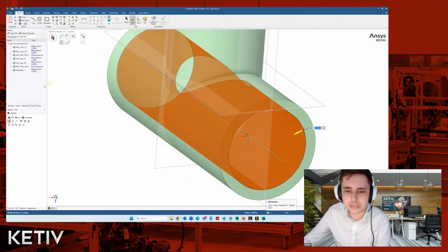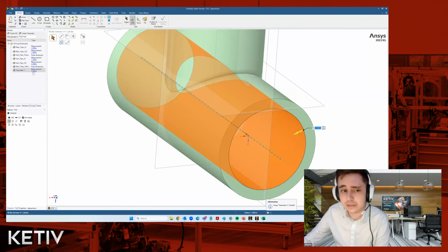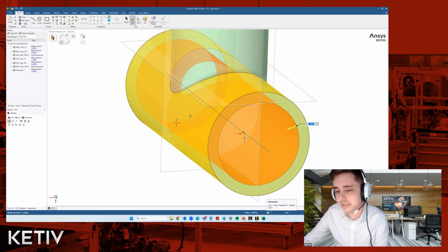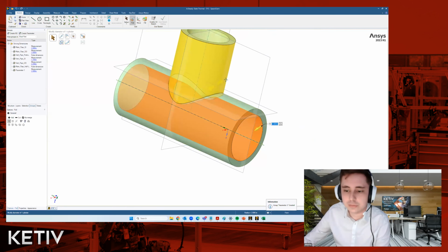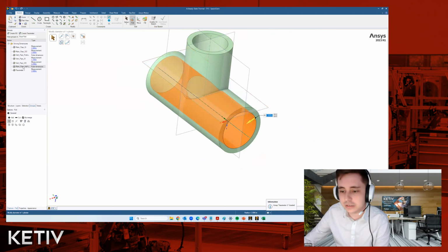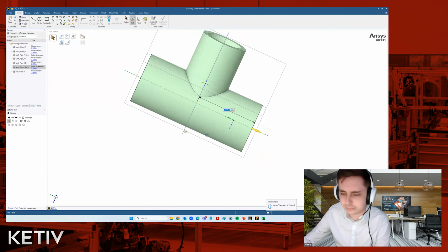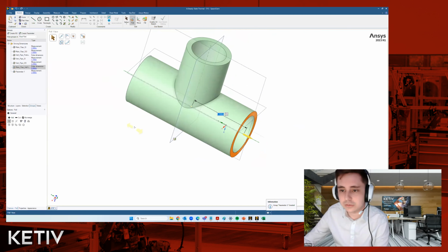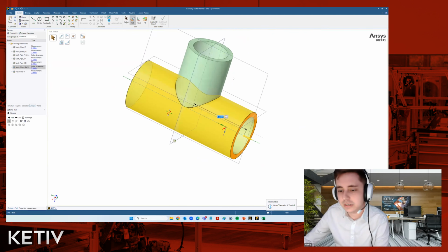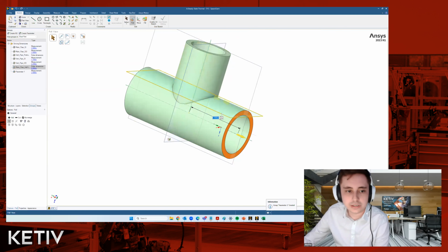So that's how you add any kind of parameter that you like. And of course, it can be much more complex than that. For instance, we have this pipe half length here, which I've created as a constraint. And you can actually make it so that you can impose a symmetry condition. And then if I were to edit this length, say to 6 inches, which it should be, then it's actually going to be reflected on the side.